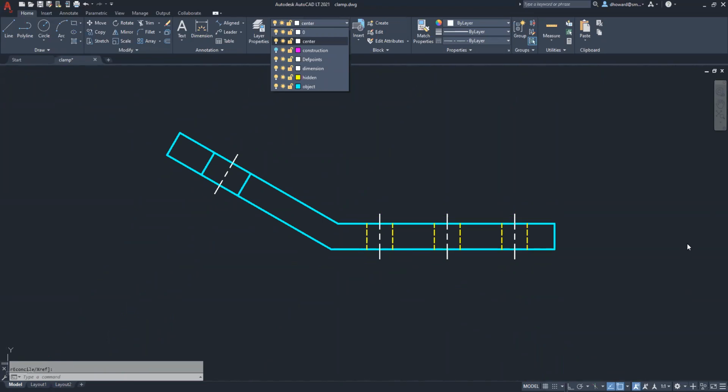You know, I take it back. We've got radii on these corners. The fillets and rounds are 3, so let's do that. F, enter, R, enter, 3, enter, and we'll hit all these corners. On the bend, it looks pretty square here, but I am skeptical of that.